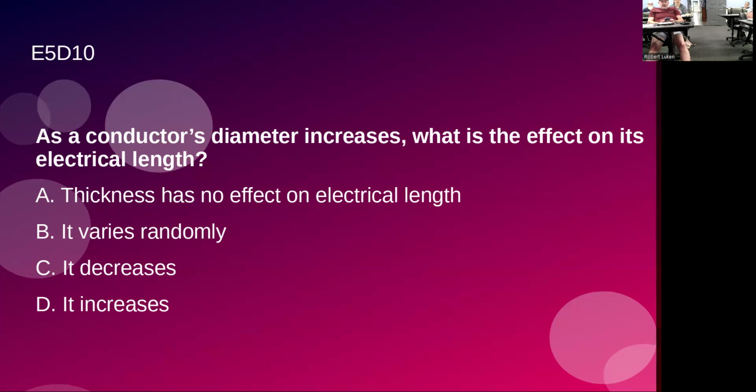It looks like it increases by a factor of 3 compared to the decrease of the inductance. So the product of the two becomes greater. And the resonant formula is, remember, 1 over 2 pi times the square root of LC. So if LC is a bigger number, then the resonant frequency result is going to be less because you're dividing it by a bigger number. But I can't necessarily prove that either.